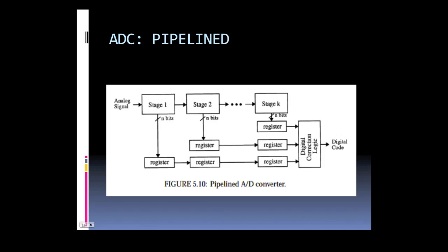An advantage of utilizing a pipelined converter is that they allow for digital correction schemes to eliminate or reduce errors generated in the analog circuitry. Digital correction can also be achieved by employing higher resolution ADC and DAC circuits in each stage so that errors in the preceding stages can be detected and corrected digitally prior to the final output stage.